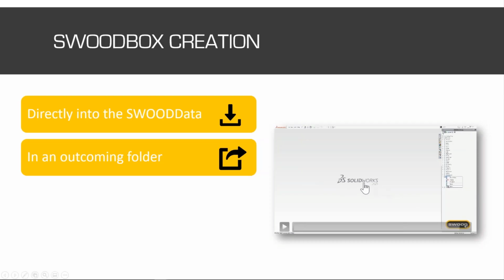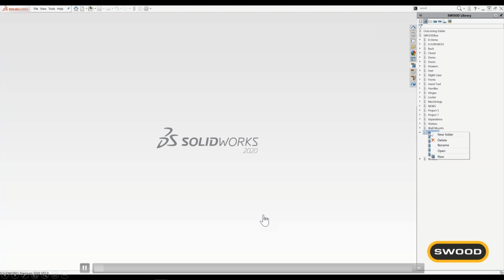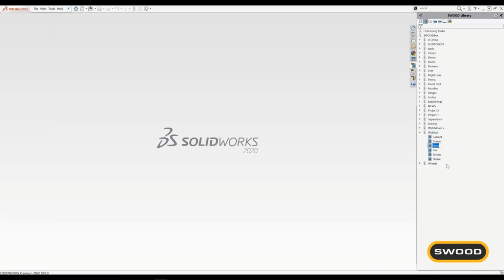Into the library on the right, you select the folder where you want to create the new SWOOD box, and then you right click and select new SWOOD box. This way, you are creating a SWOOD box directly into the SWOOD data and into the webinar folder in this case.